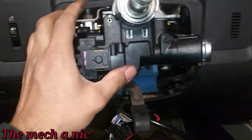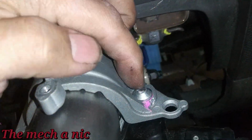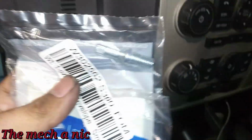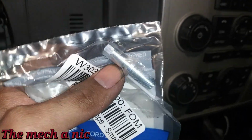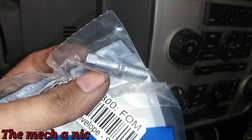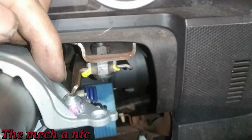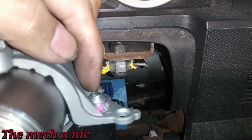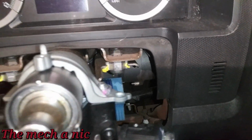And the only thing that's holding this on now is this one bolt right here, but you can see it has no head on it, and that's this bolt that we bought right here. Once it's torqued down to spec, it's actually designed for the head of it to just shear right off. It's kind of like a tamper proof bolt. It's a one-time use. You install it, and in order to remove it, you grab a cutoff wheel and cut a slot in it, and it lets you use a flathead screwdriver to remove it. So I hope that makes sense.